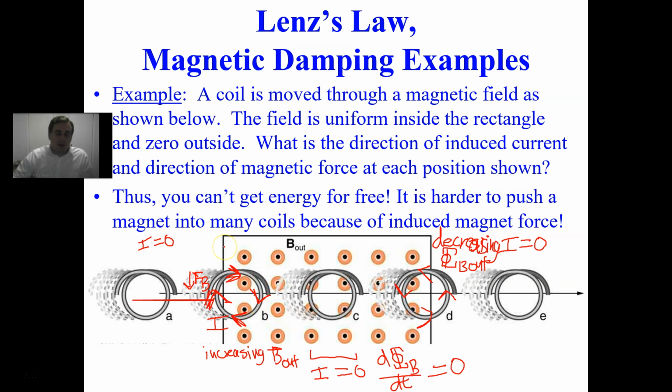But notice on the bottom here, the current is to the left. The magnetic field's out of the page. The magnetic force is going to be upward. Notice these two will exactly cancel because they're the same length. Notice over here, again, to the left, out of the page, so it's up. So right here, the magnetic force is up. And then right down here, the magnetic force is downward. That's both based upon right-hand rule 1b. Notice the current is going to cancel on those places.